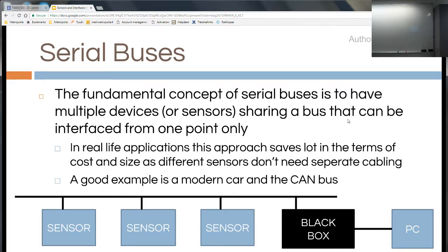In principle you can even have just wires coming from the sensor directly to this microcontroller board, and you can then distribute the wires where you want. If you had long analog wires and small signals, you would end up having problems with all kinds of noise induced to those lines. So that way we have this kind of buses overall.